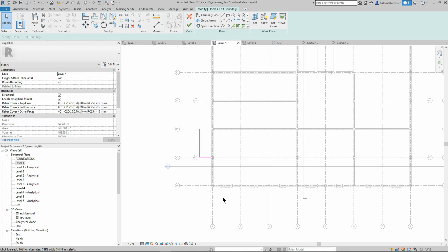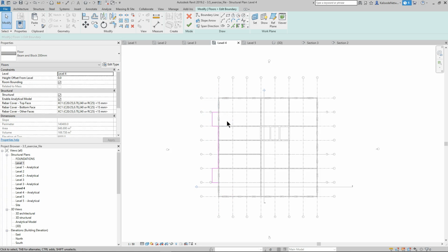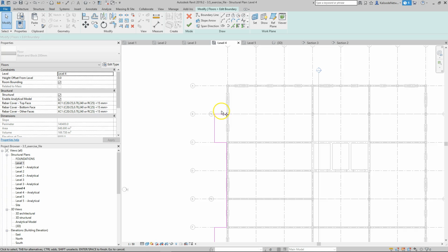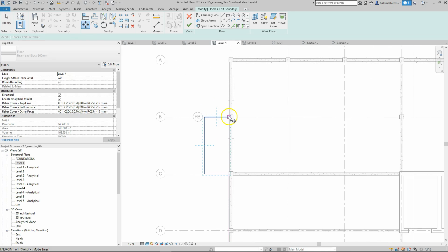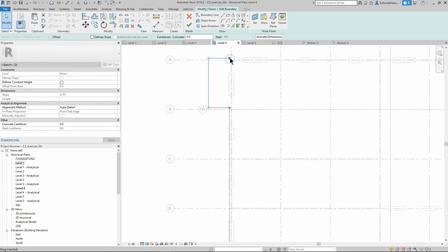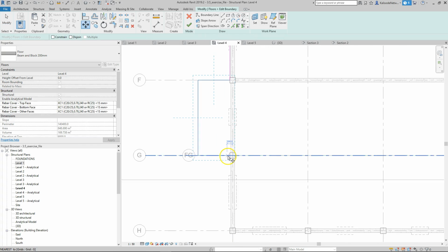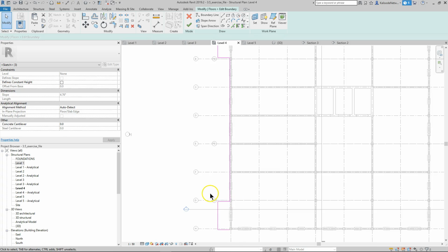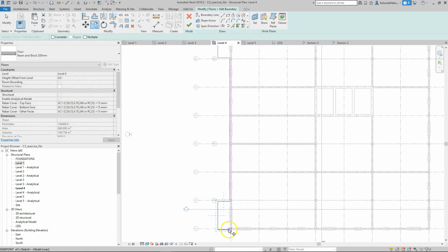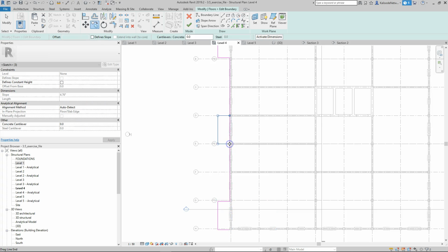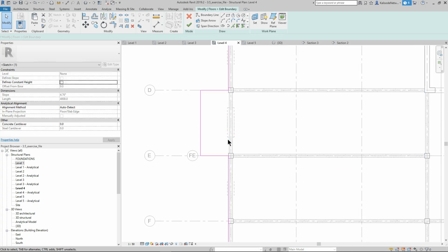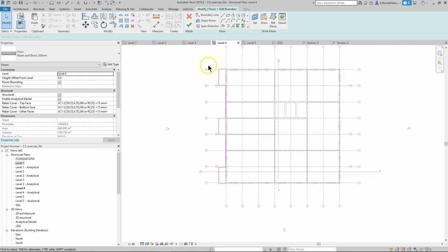So I've saved just one of these four sides. I will shift the balconies thanks to the move command, MV shortcut. I click here on the edge, exactly, and I select these two, move command. I will move this, and you can see the magenta line is connected, it's stretching too. And this is the copy command. I copied one balcony, and remember that the line needs to be continuous.